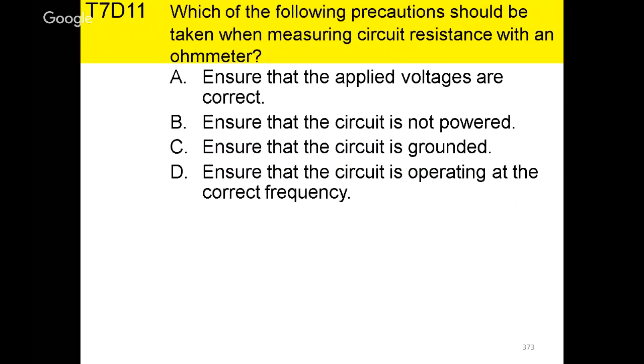Okay, which of the following precautions should be taken when measuring circuit resistance with an ohm meter? Now, you've got to be really careful when you're doing this. You can't just throw your meter on the resistor or check really any component passively if you have voltage turned on or applied to the circuit.